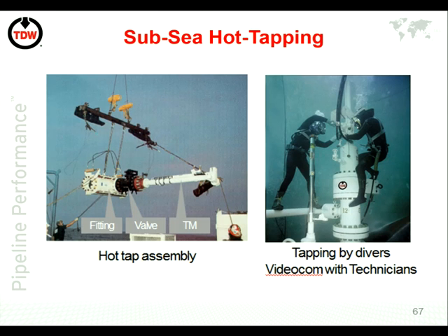Everything was assembled at site. So we put the fitting on, we put the sandwich valve on, we bring the tapping machine in. You haven't got that luxury 200 metres under the sea. You've got to do the assembly on the vessel. So that's the tapping machine, that's the sandwich valve or the valve that we'll use, and the fitting we talk about is, say, hyperbaric welding can go on.